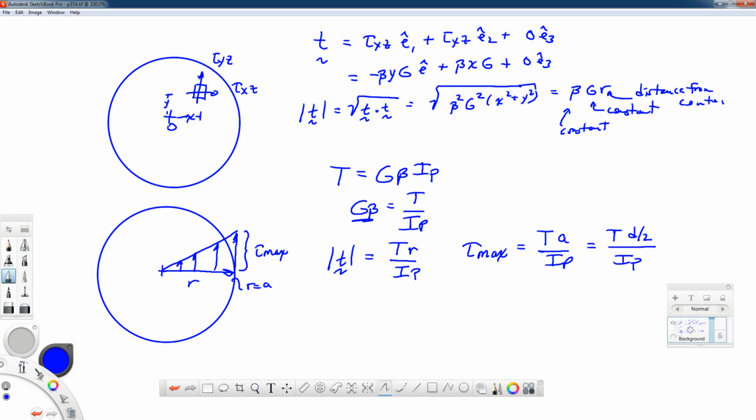So again, this is another example of using the semi-inverse method. Some people may call it the St. Venant semi-inverse method. This is another example of just using that method to assume a certain displacement field, or we've done other examples where we looked at stress fields that would go to strain fields, integrating our strain displacement equations to get displacement components, or seeing how that works out, and coming up with some idea of how this bar's stress distribution or displacement fields or strain distributions look after these particular fields are applied.